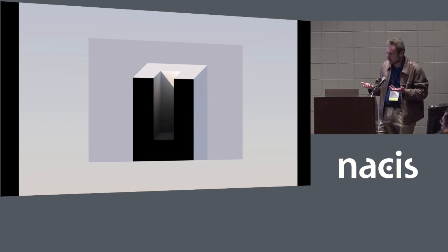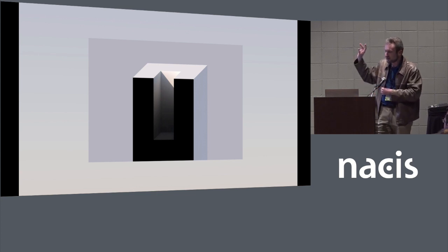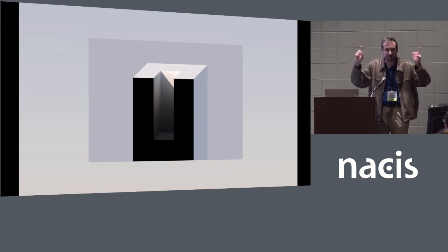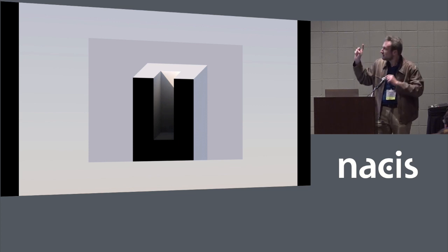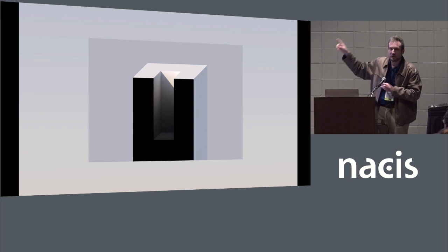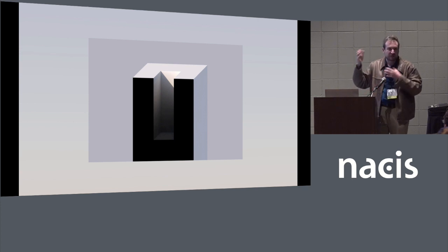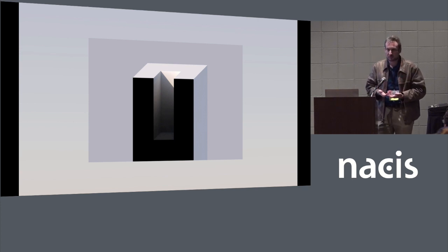Again, I don't have time to go into detail on it, but it turns out that despite the fact that this is very slow to calculate in a lot of algorithms, because you have to sample how much of the sky a point can see, this is a curvature problem, which means you can use normal maps and this pyramid scaling technique to get this much faster. It's basically just combining a whole bunch of rasters together.